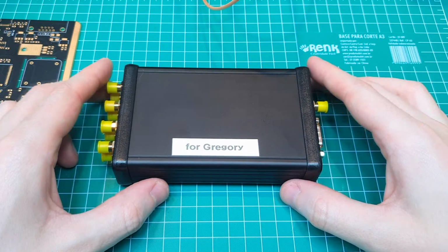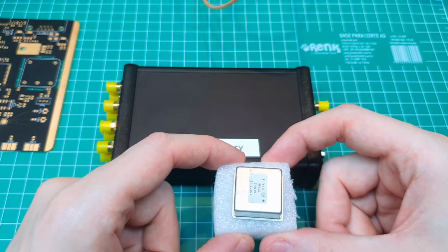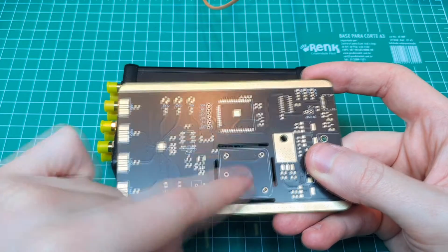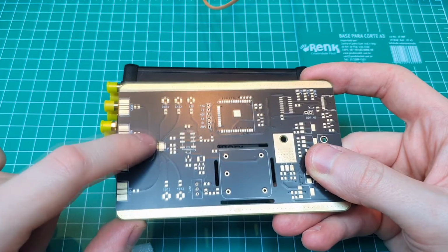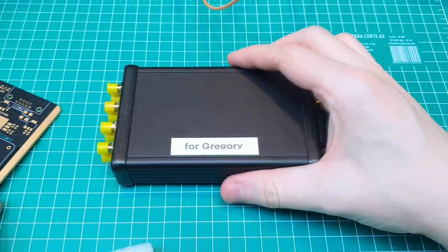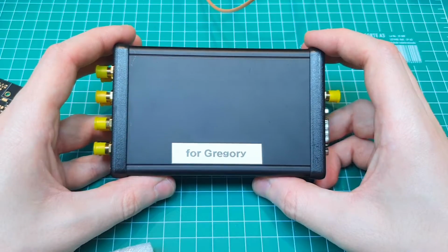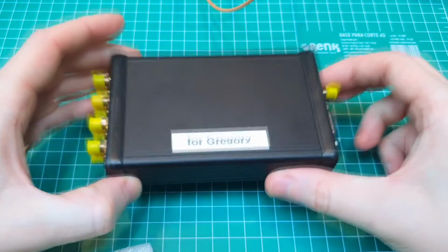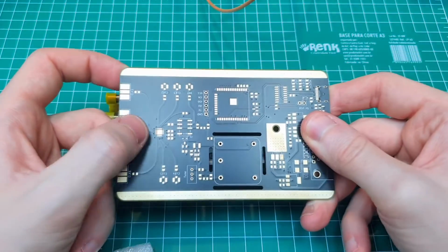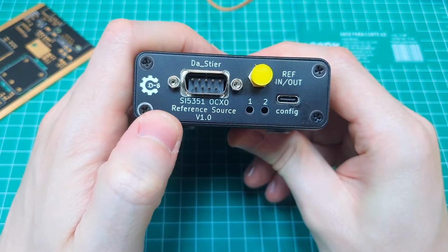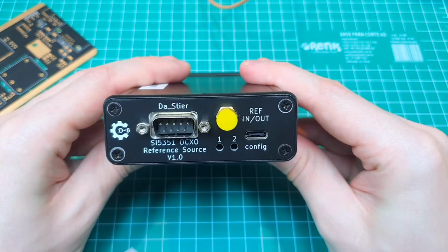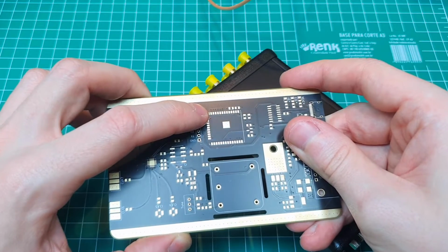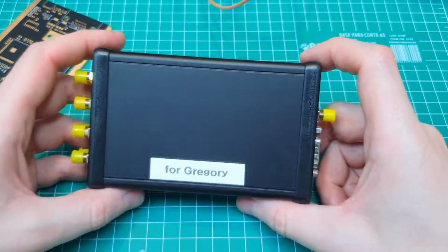So the main idea of the device is that we have an Ovenized Crystal Oscillator inside, a modern microcontroller, the ESP microcontroller, and we have a clock distribution system IC that generates 8 independent clock outputs. When I first got an email about this, I thought that it was a common clock distribution system, but thinking better today, we have a very powerful IC here, the SI5351. As it has this very modern IC and a USB port, and as we can change the firmware of the microcontroller, this actually becomes a very powerful signal generator.